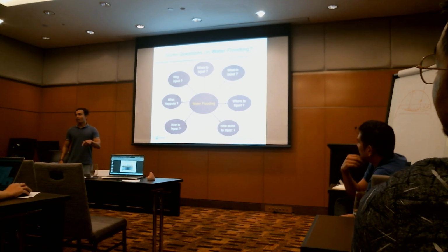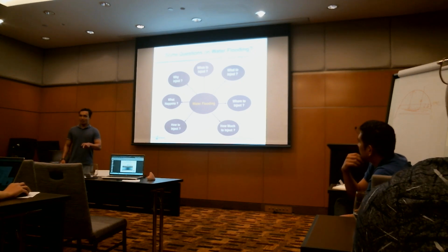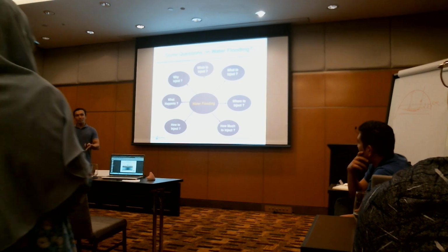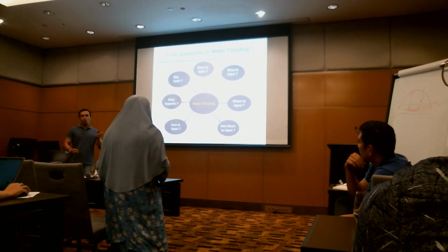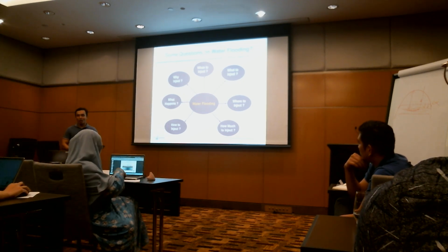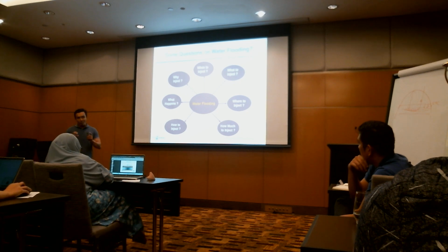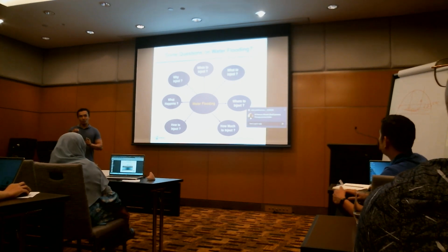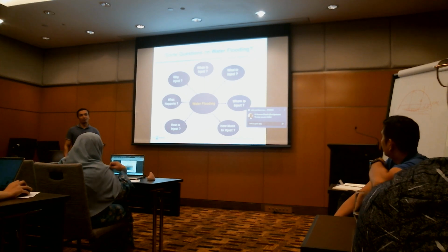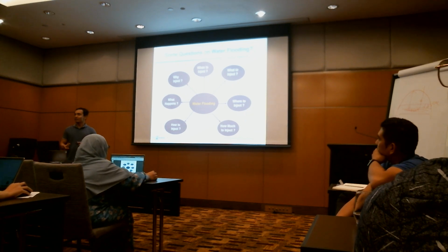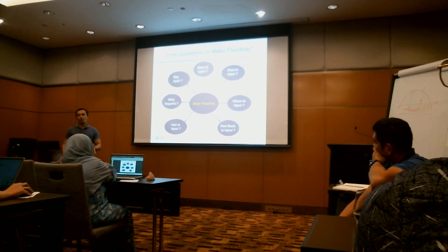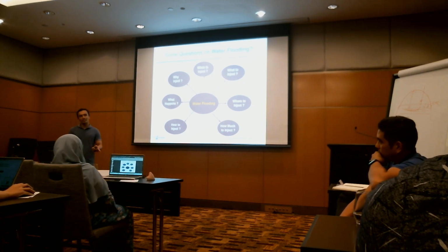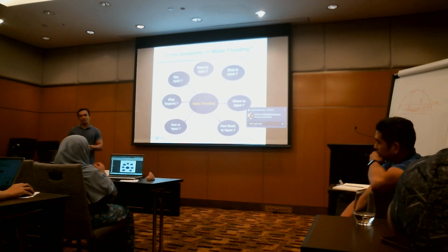And remember, as you deplete the pressure, you want to compensate the pressure, so you have to inject more. A lot of water you inject to compensate the voidage that has been withdrawn. So it's maybe not a good idea to inject much later. You just spend a lot of money, and also you might not get the best sweep efficiency.